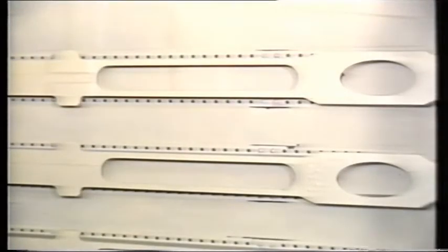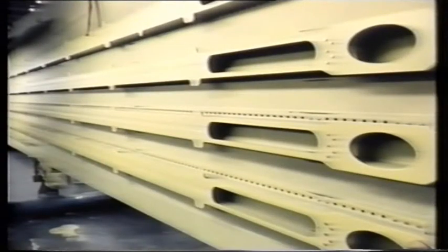Surge tanks are located in the tip of each wing and in the right tip of the horizontal stabilizer. Air and excess fuel are vented to the surge tank by vent tubes or hat-shaped stringers, which are attached to the upper wing structure. Fuel returns to the inboard main tanks and the air vents overboard.